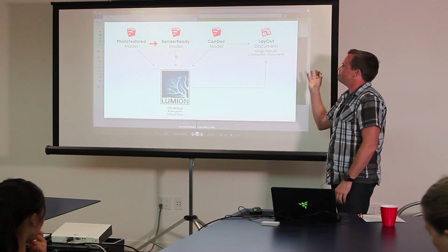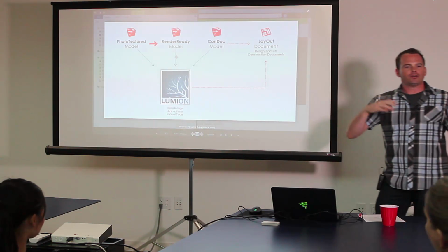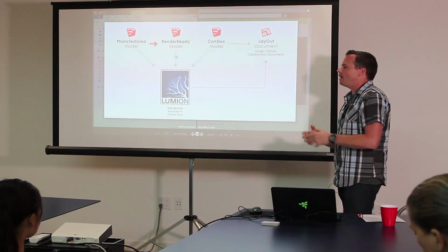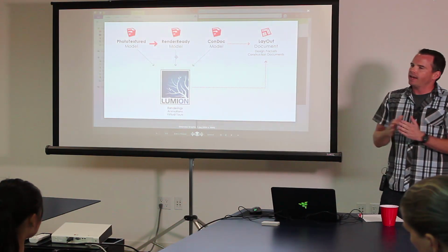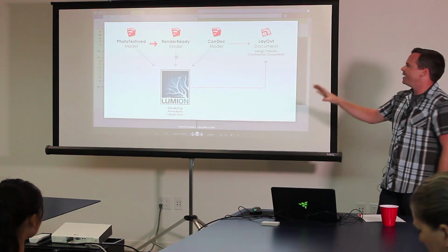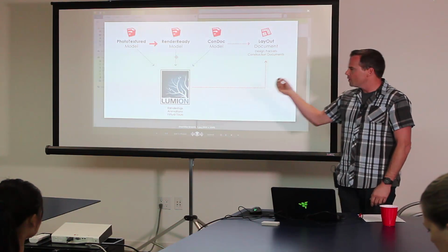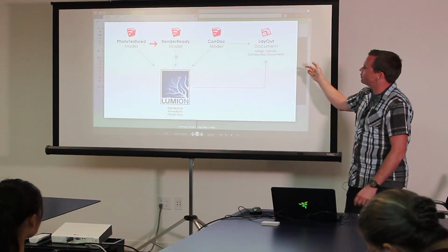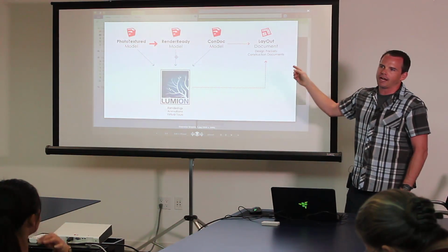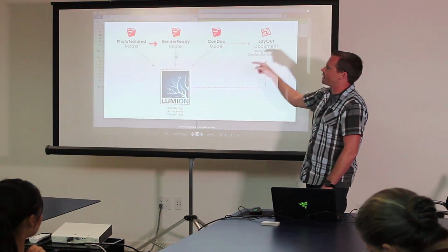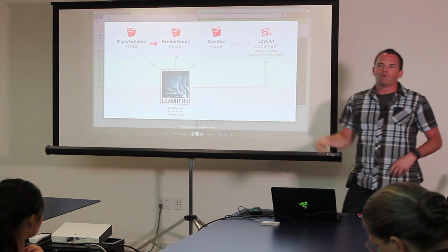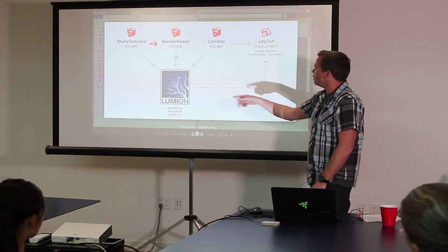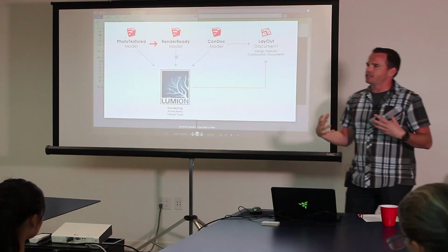Layout, if you're familiar with 2D CAD, is the paper space for SketchUp. So Layout is where you take your 3D model and flatten it and put it on a page and then set it to an architectural scale. So these models, as they march along and evolve, they go into Layout to create design packets and construction documents. And at the same time, those exact same models head down into Lumion, where we set up animations, virtual tours, and still renderings. And then those go back up into Layout and create your design packets.